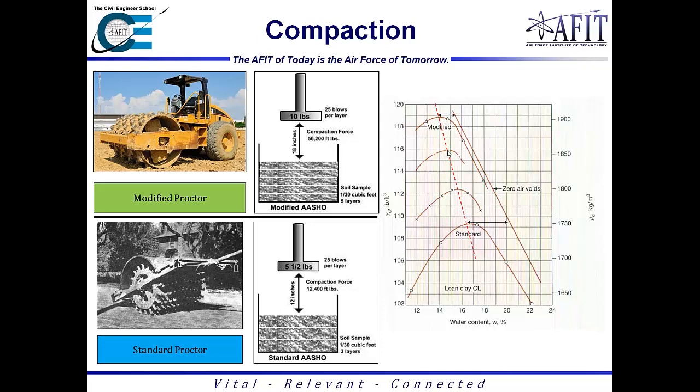So just something to keep in mind. The more compactive force you use, the higher the dry unit weight will actually be in the end.